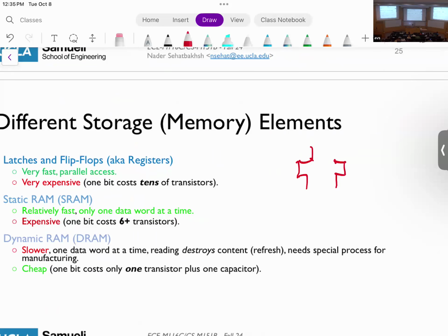It's like the transistors are connected this way. And then there are 2 selector transistors here. So this is an SRAM. This is your VDD, and this is your ground. So SRAM looks like this. Typically, you have 6 transistors connected this way. Again, the internals of an SRAM are not a concern for you in this class. But if you're interested, go and check it out. This is used for storing only 1 bit.